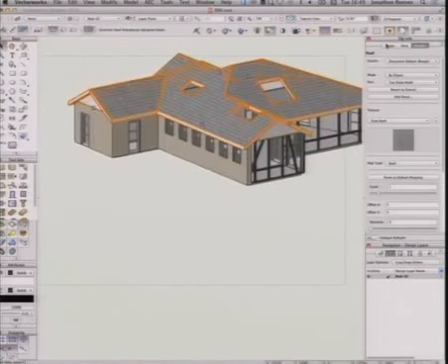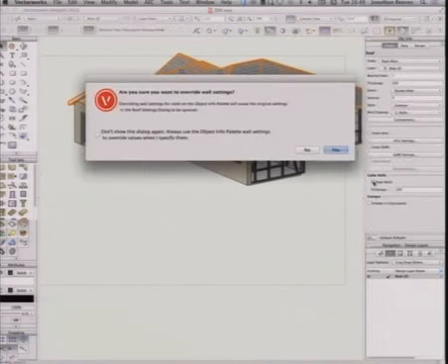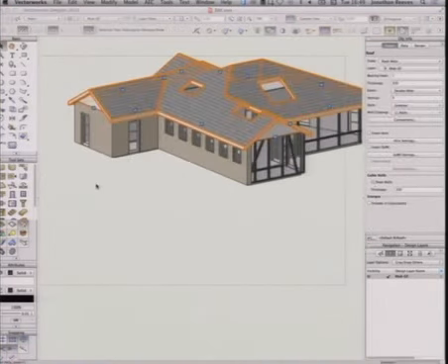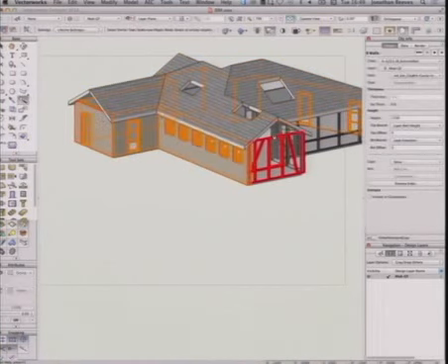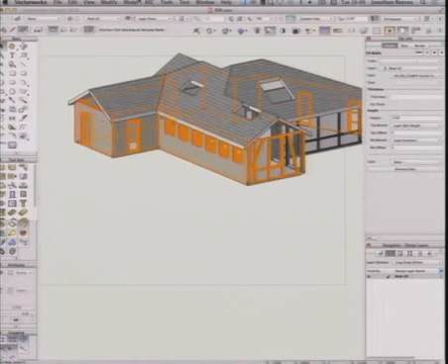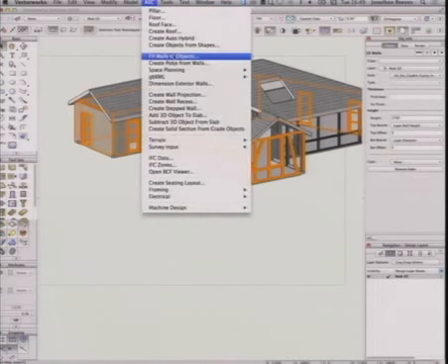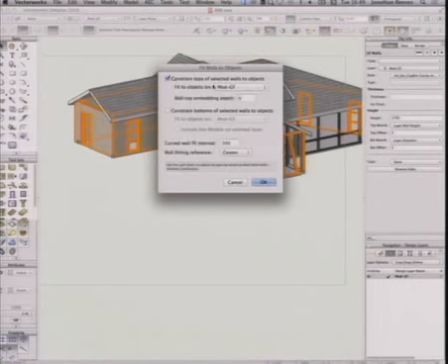Okay, so on my roof there, I'm going to turn off the walls. And I'm just going to do one more little command where I select my walls. I'll try this one as well. And I'm going to basically fit the walls to the objects. So essentially, I'm fitting those walls up to meet something that I've modeled on a different layer.